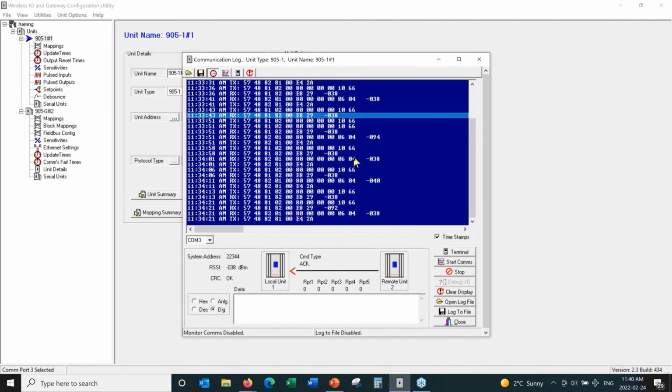Okay, so we've talked about the RSSI values here, and you can click on any line, and it'll show you what the RSSI is, same as the number that you'll see up here. And as we go through each line, it shows you what type of message was sent back and forth. Okay, so here we go. It's another one. Register 4320 is commanded to be off on the gateway radio here. And the next message is the gateway sending an acknowledgement back that, yes, I got that message.